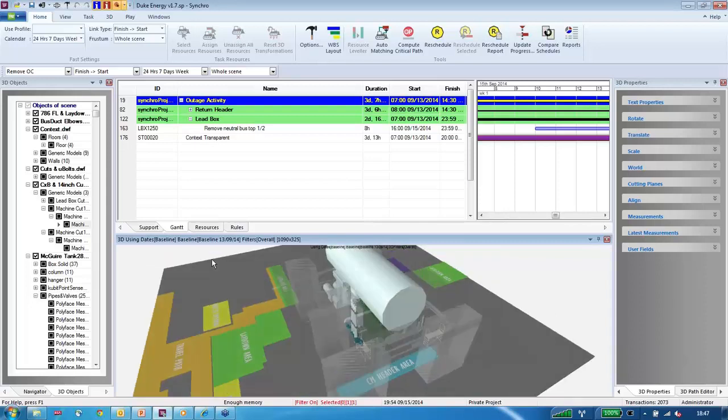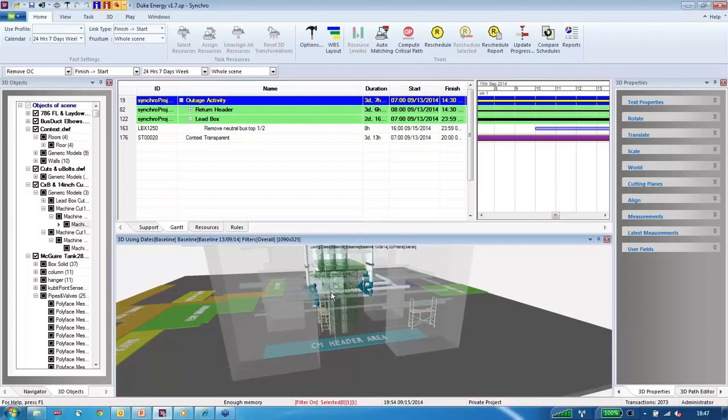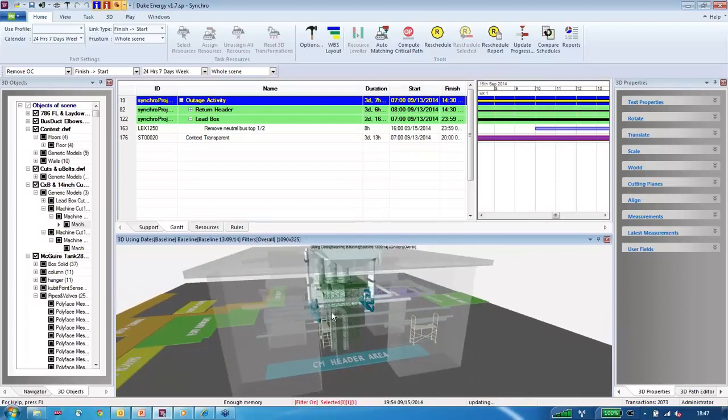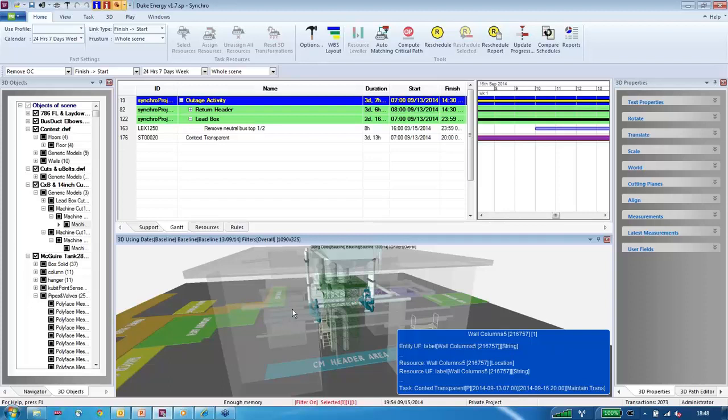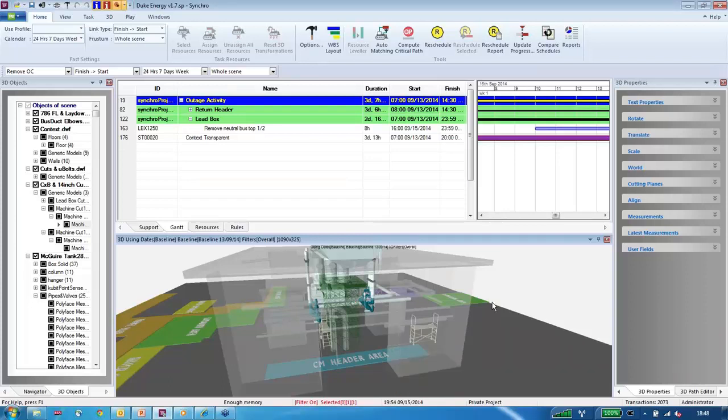All right. Another question that I have is, do you see value in exporting model data back into P6 from Synchro? That one depends. I did not do it. I know it's possible. I know of other construction delivery teams that are doing this, and with the right team and the right process, yes, I do see that value. In particular, Synchro has the capability for new construction. Again, in this situation, we're taking something out, putting something similar back in. But the easiest way to describe this is, say you've got 100 doors to install on 10 levels. Sometimes you'll build that in Excel and import into P6, or you'll try to do a fill down in P6, but that's tough to do, to build up all those activities.